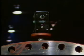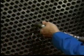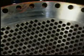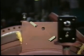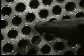When it may be considered too difficult or time-consuming to use the pressure or vacuum methods, the tone method should be used. Blow all the tubes free of debris and liquid, which will block the sound. UE Systems WTG-2SP warble pipe tone generators are used. Use as many tone generators as may be necessary in order to achieve as uniform an ultrasound field as possible around the tube bundle. As an example, place one in the inlet port and one in the outlet port. Proceed as with the other leak detection methods, scanning for the sonic penetration of the warbling tone.